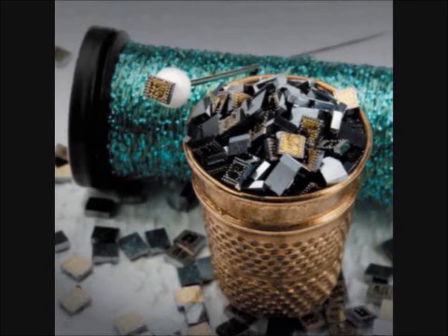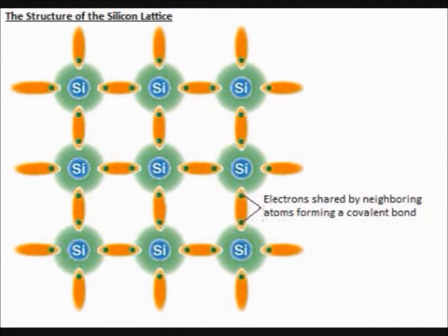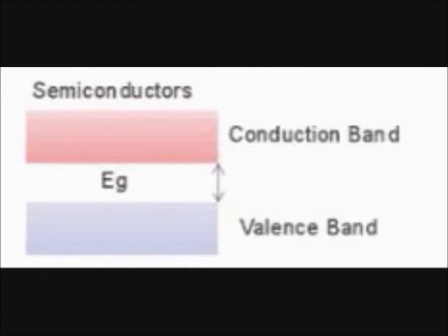Examples of elemental semiconducting materials would be silicon and germanium. Each semiconductor atom has 4 valence electrons, and each semiconductor atom is bonded to 4 other such atoms in a crystal structure. This lattice structure results in the band and energy gaps as discussed above in semiconductors.